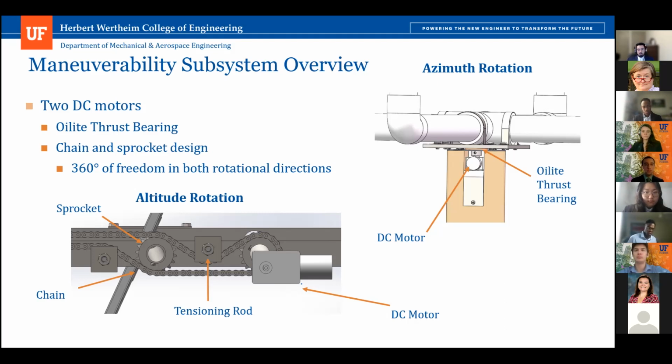When you mentioned that you were looking at fatigue analysis, you said you didn't need to do fatigue analysis of the wood because it's a brittle material. Yeah, that's what I had estimated. Pretty much just that, as long as the maximum stress didn't go over the yield strength of the wood, that would be fine.